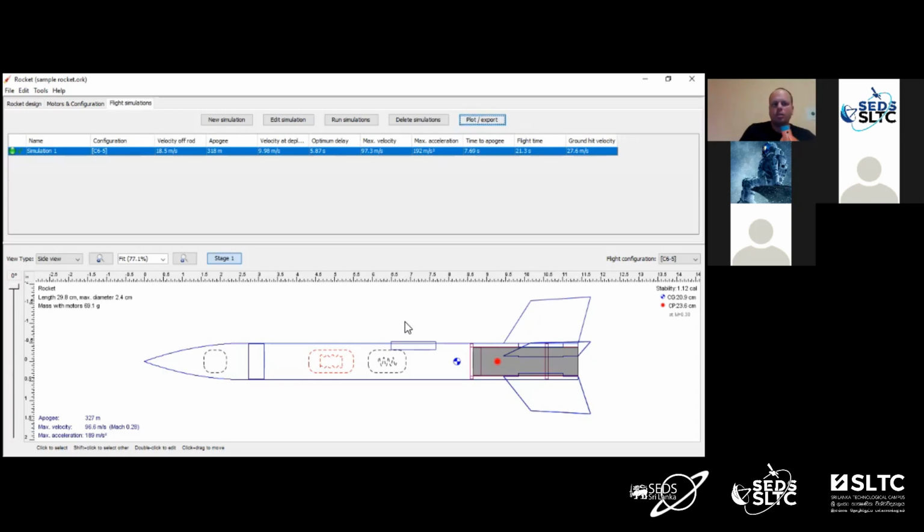I mentioned vent holes last time. If you'll notice, there's a little hole opposing on each side. That's to allow the cold air inside to vent out. We need the hot, burning little pieces of propellant to fly up and ignite the upper motor, so we need to allow the cold air to vent out. That's what these two little opposing holes are for. But again, the bottom motor burning up will ignite the top motor. That thrust will knock the lower stage off, and it'll continue on up. So with the black powder motors, it's super simple.